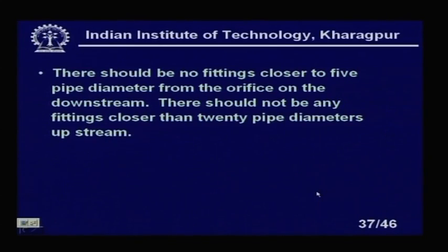Otherwise, what do you mean by near? In engineering, you must quantify. You cannot say just qualitatively very near or very far. There should be no fittings closer than 5 pipe diameters from the orifice on the downstream. Same, no bending, no elbow, no valve, no T.